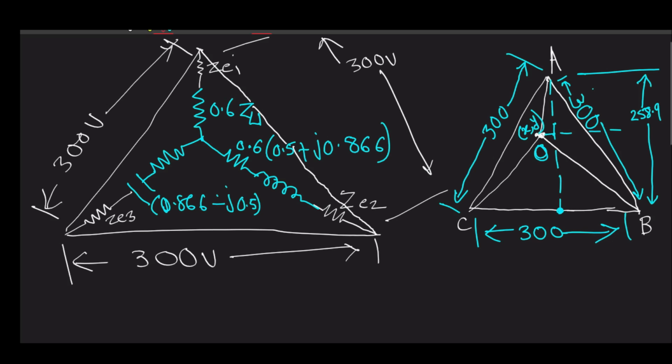Try to understand that, as I have already mentioned, the primary side line voltage is constant, so your secondary side line voltages are also obliged to maintain a constant proportional relationship with the primary. So this 300 is coming from 15,000 by 50, which results in 300. So there is nothing new here. However, the important thing to note is that all the phases we are having